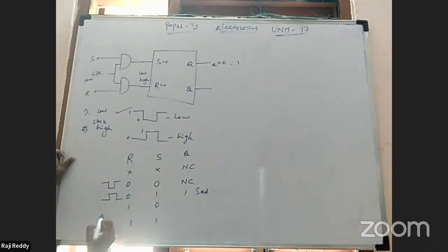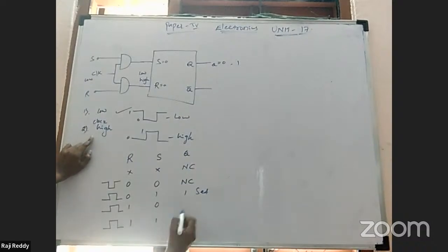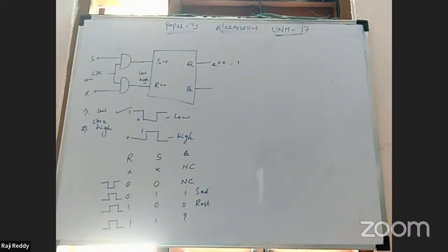Set, reset conditions. Again, continuously we are giving positive triggering, or positive clock pulse, nothing but high clock pulse. So it goes to reset, then next the previous data. Then when you give both the inputs 1 1, it won't work. That is nothing but prohibited. In another way, this clock pulse indication is a negative clock triggering. These are positive arrows. You can express it in this way also. It means these last three entries are positive going triggering, and the first one is negative going triggering. Like this, we have to explain one entry stepwise.